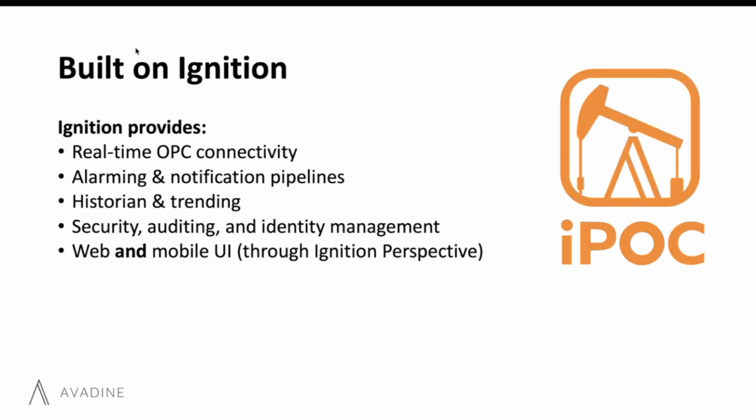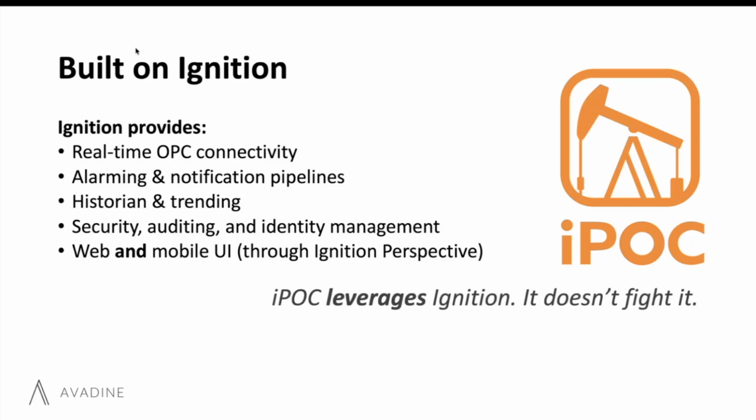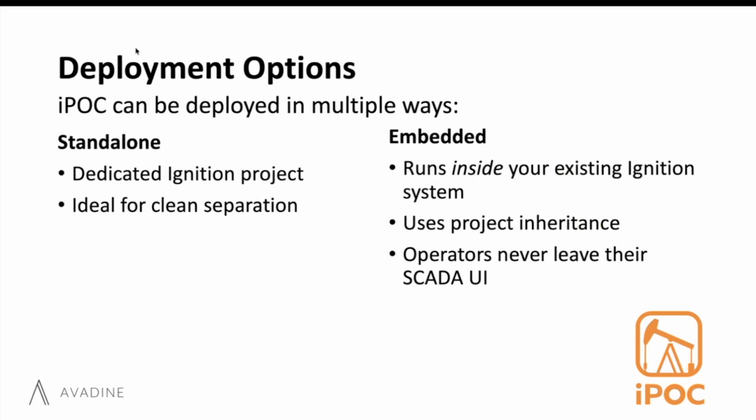So iPOC is built on Ignition. Ignition provides the real-time OPC connectivity, alarming and notification pipelines, historian and trending, security, auditing, and identity management, web and mobile UI right out of the box through Ignition Perspective. So these are all the things we love about Ignition, already comes right in the box with iPOC. And iPOC leverages Ignition, it doesn't fight it. So we definitely are working hand in hand.